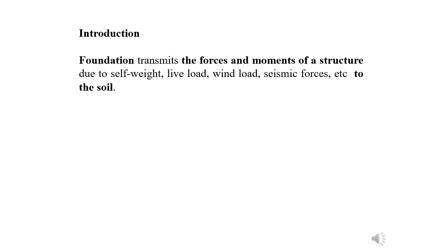You can see here the footing of the foundation is going to be influenced by the self weight, live load, wind loads, seismic forces. Many types of forces are going to be experienced by the structures. So ultimately, the foundation transmits the forces and moments of a structure to the soil. Here when we say foundation, we mean footing. Footing is the bottom part of the foundation.